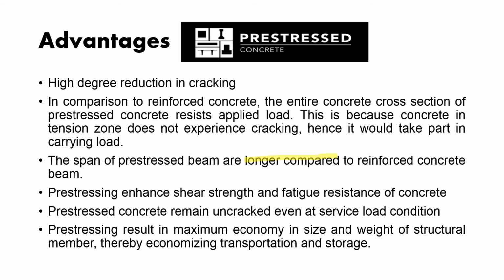Pre-stressing enhances shear strength and fatigue resistance of concrete compared to normal concrete. And pre-stressed concrete remains uncracked even at service load conditions. Pre-stressing results in maximum economy in the size and weight of structural members, thereby economizing transportation and storage. So once you use the pre-stressing method, it will reduce the size and weight of the structural members, so it will achieve economy also.